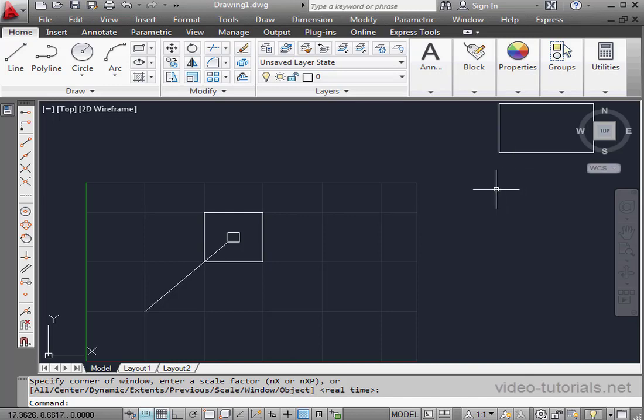And of course, to toggle the Snap to Grid function on and off, we can use the Snap switch in the status bar, or just press F9. And this concludes our lesson about working with the grid in AutoCAD.